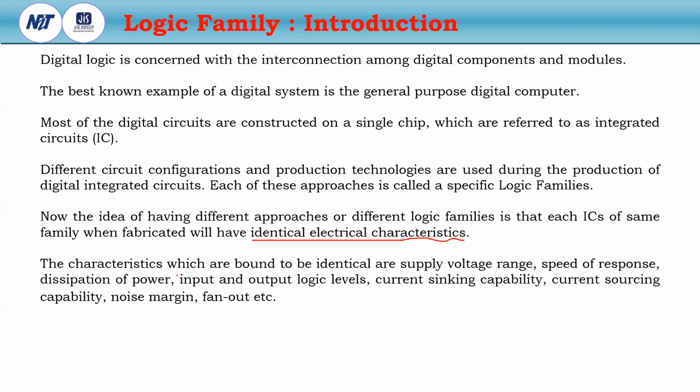The characteristics which are bound to be identical are the supply voltage range, speed of response, dissipation of power, input and output logic levels, current sinking capability, current sourcing capability, noise margin, fan out, etc. I will discuss it later in more detail.